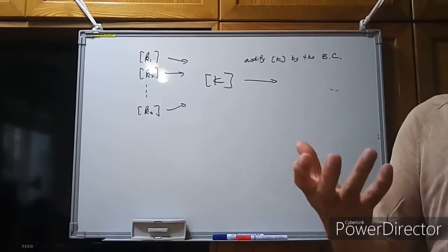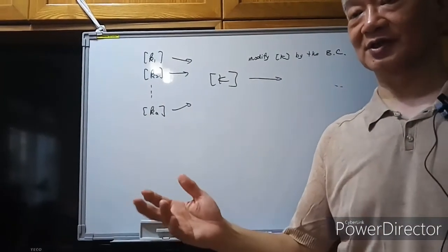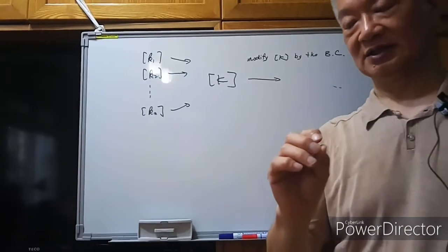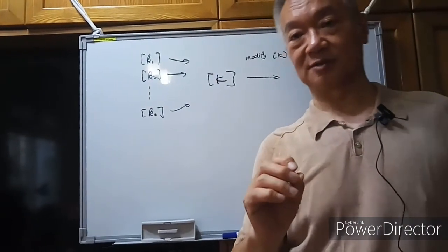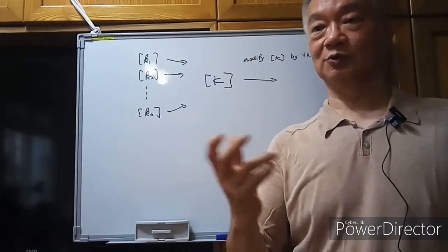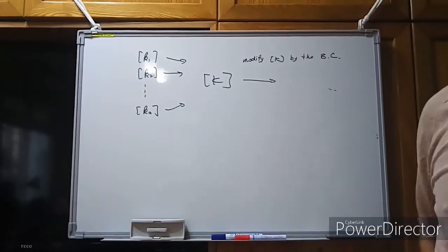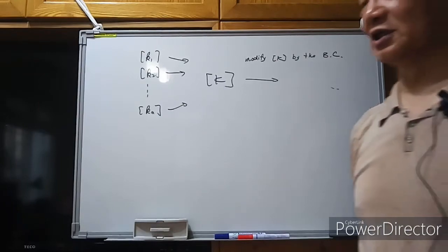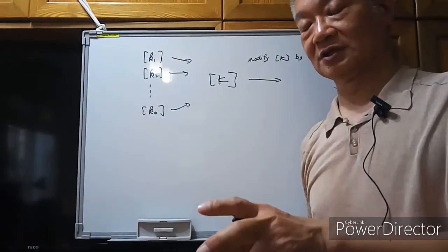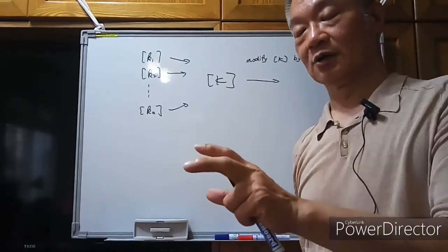But for some elements, we have 3 points with unknown displacements, but one of the nodal points is connected to a support. Then we know the displacement, but we don't know the reaction. So when we formulate the displacement functions for this element, we need to consider only the 3 nodal points which could move.